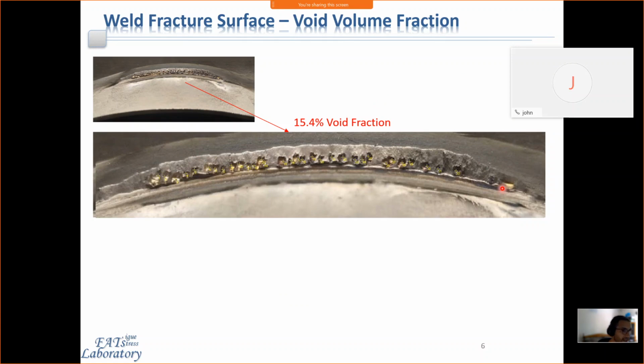So it's whatever plane the weld actually failed on. It's not exactly in plane with the top member. It's somewhat in plane. It's what you would expect, kind of the plane of maximum critical stress in the weld itself. It's a slight oblique angle. Hopefully that gives you the right answer for what you're looking for.